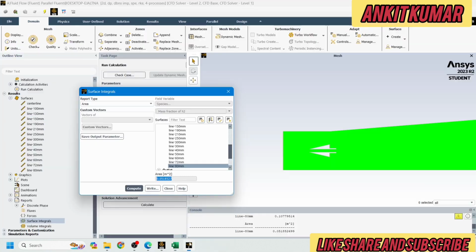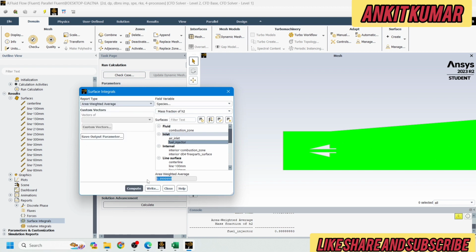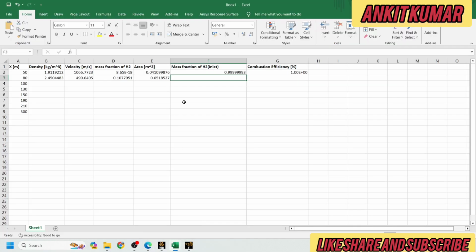Again, the mass fraction of the H2 inlet. Since the mass fraction of H2 inlet is constant, whatever mass fraction is coming from the fuel injector is constant. So we will get the same value again and again, 0.9999, around 1 only. It will be the same for all. So we can try: bring the cursor to the bottom corner and a plus icon appears. Once the thin, filled black plus icon comes, not the thick hollow one, press the left mouse button and pull it down up to where we require, up to 300 mm, and then leave it. It will give the same value, around 1 only, because the mass fraction of hydrogen coming from the inlet is complete, 1.